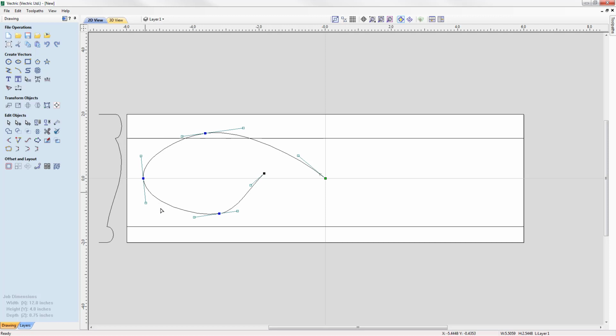Okay, so just working our way around the rest of the nodes, we're just going to pull at the spans, pull at the handles, and just really edit the shape until we like the curvature that we've got for the stalk. So we're going to start by looking at this control point here to edit the shape of the stalk.